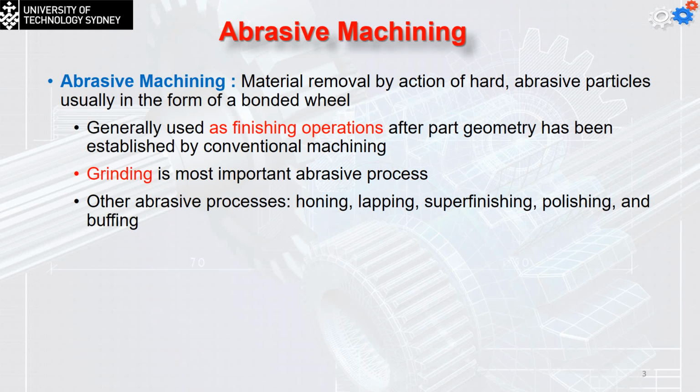The coarse one is going to give you a worse surface finish, and the better surface finish is going to be with the fine one. Now, for the coarse and the fine, which one is going to contain more particles? The fine one or the coarse one? The fine one, because the particles are smaller in the same area, so it's going to have more density, and that's what we're going to talk about when we describe the grinding wheel.